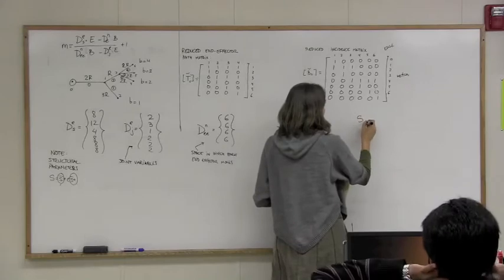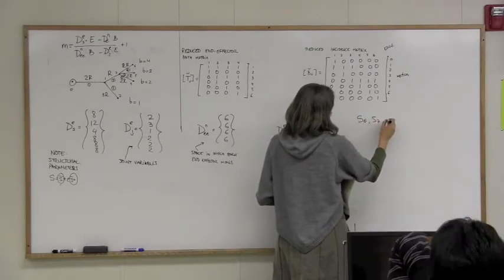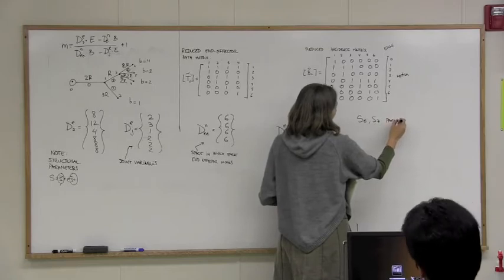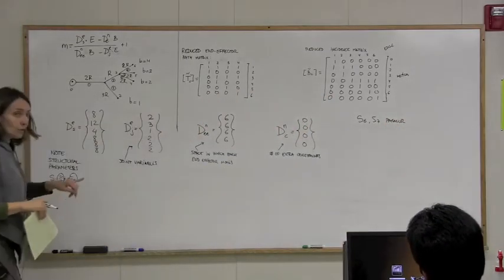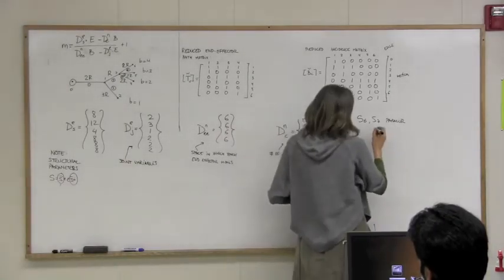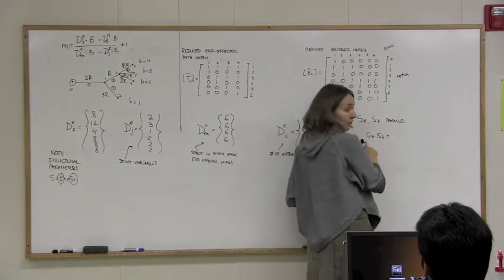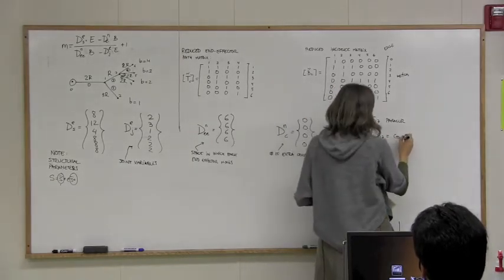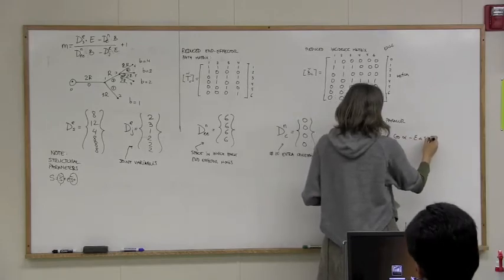So you would say S6, S7 are parallel, and then you could impose conditions of parallelism here based on line geometry. So you would do the dot product of them, S6 dot S7, and you get a dual number there, right? Cosine of the angle between them minus epsilon A sine of the angle.